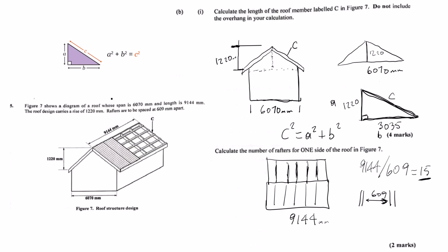So the calculation runs 1,220 squared plus 385 squared. Okay, let's see. That comes out as 1,636,625. Then you find the square root of that number. Which gives us approximately 1,279 millimeters, so about 1.28 meters. That's the calculated length of the sloping rafter. Not counting any overhang, right? Just the structural length from wall plate line to ridge line, yes.